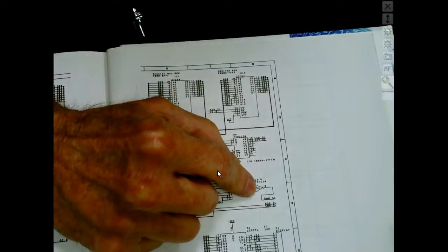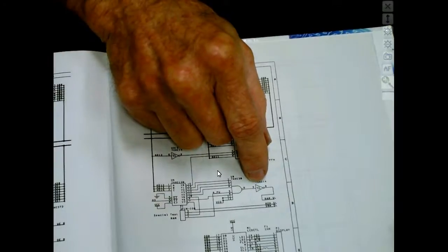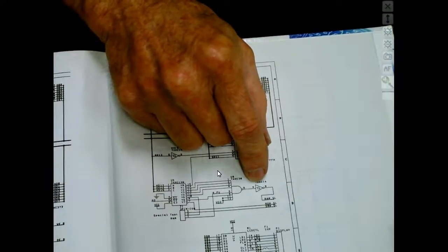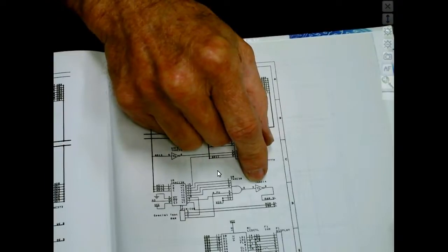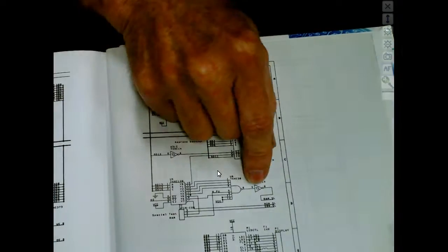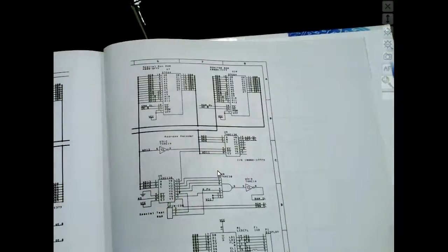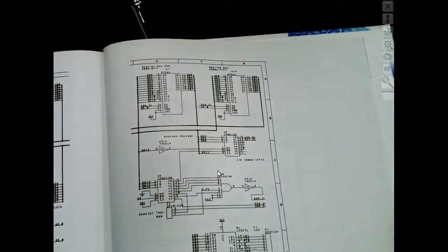Notice it's still an inverter, except this guy has no invalid states. There's no invalid input on these guys. All you have to do is exceed an upper threshold and a lower threshold. This is called a hysteresis curve symbol, by the way, which means they're not the same. So the high threshold is not the same as the low threshold.